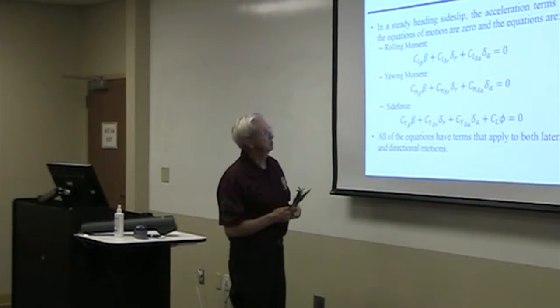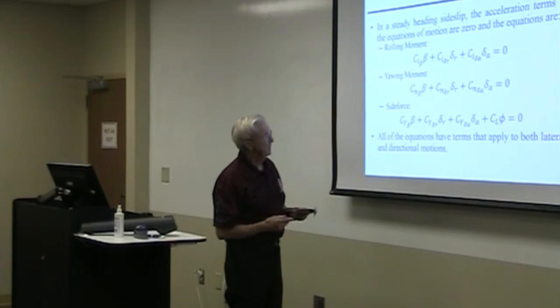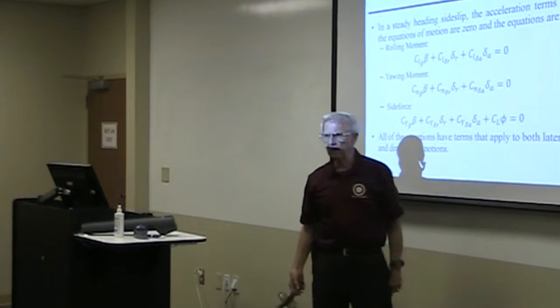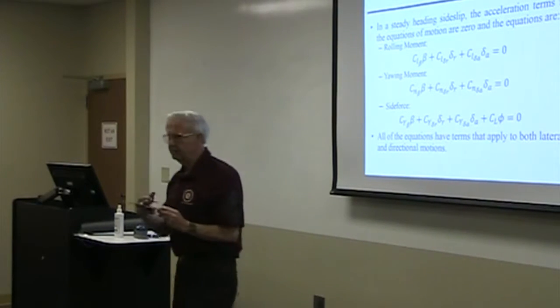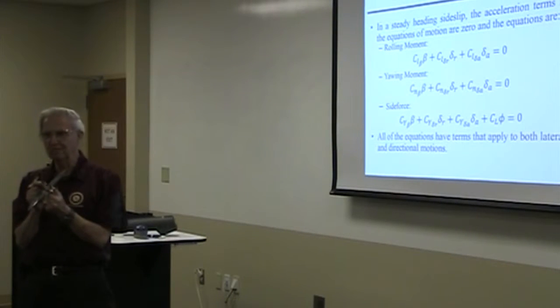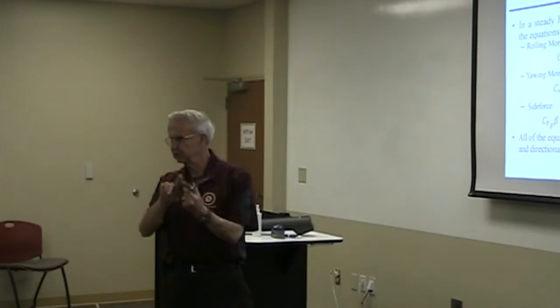These motions about these axes are coupled. Side force, this is lift coefficient and bank angle in this equation, okay? So that's the side force. You tilt the lift vector. All of a sudden the lift vector is pointing this way and not straight up.